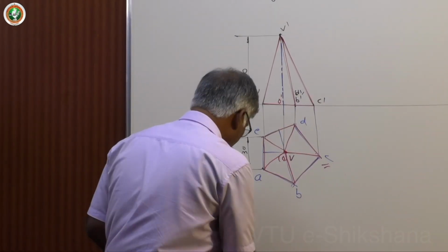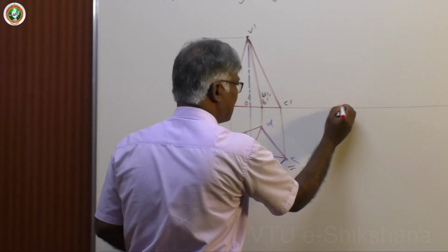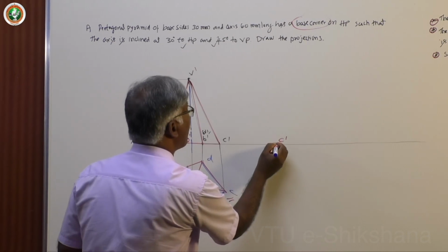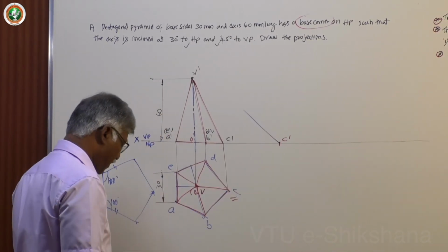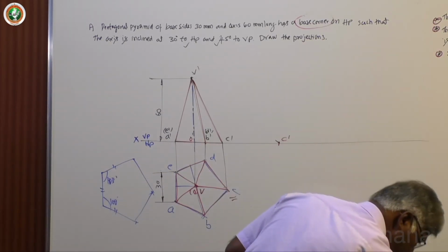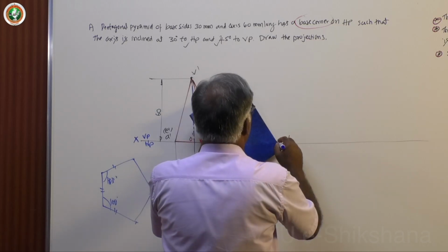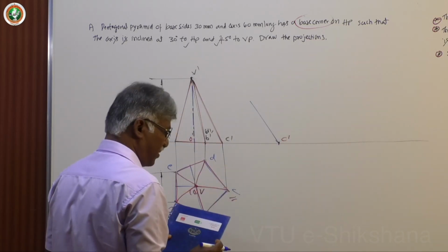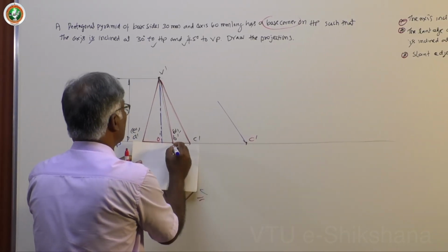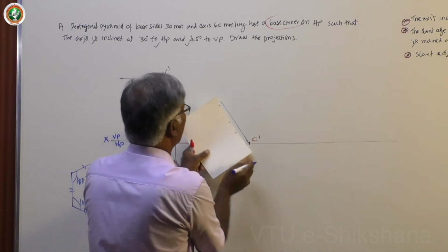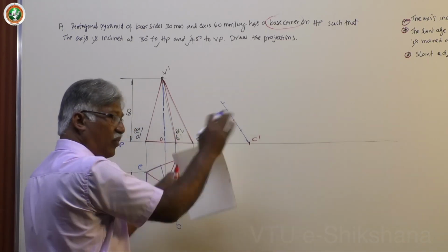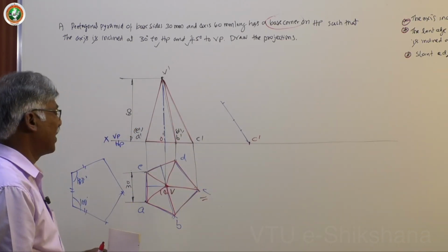First position is this C dash, you mark C dash, then draw a line inclined at 60 degree. Okay. So, because 30 degree is the reference, take 60 degree and mark these points. So, take with compass same distances, you must mark here. Suppose that if you take in this sequence, you must mark in this. If you do ulta, then problem starts. You never get the solution.